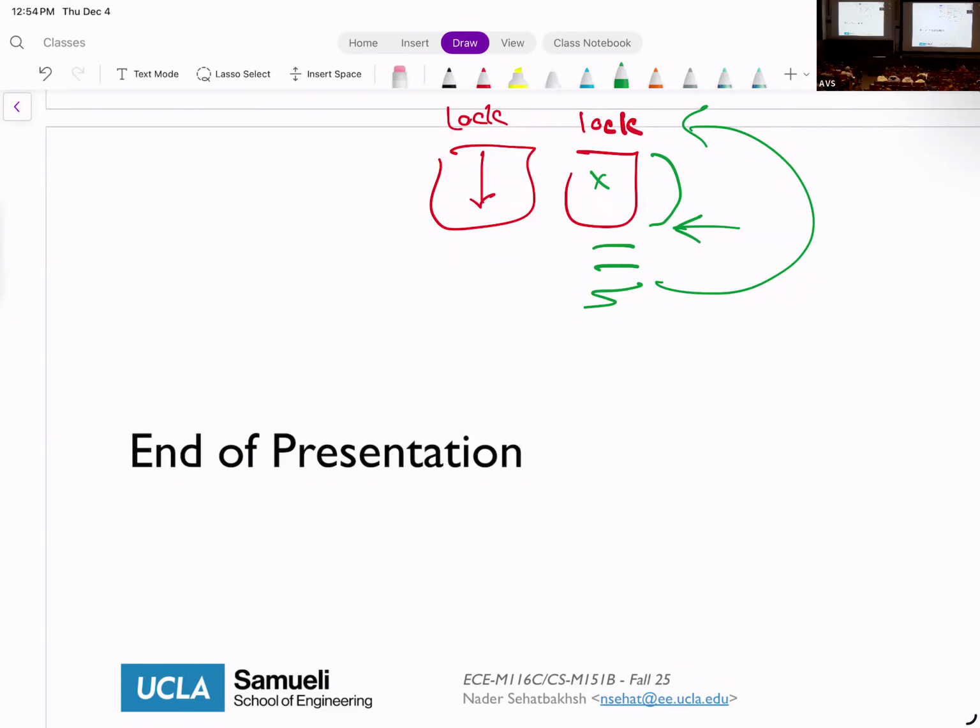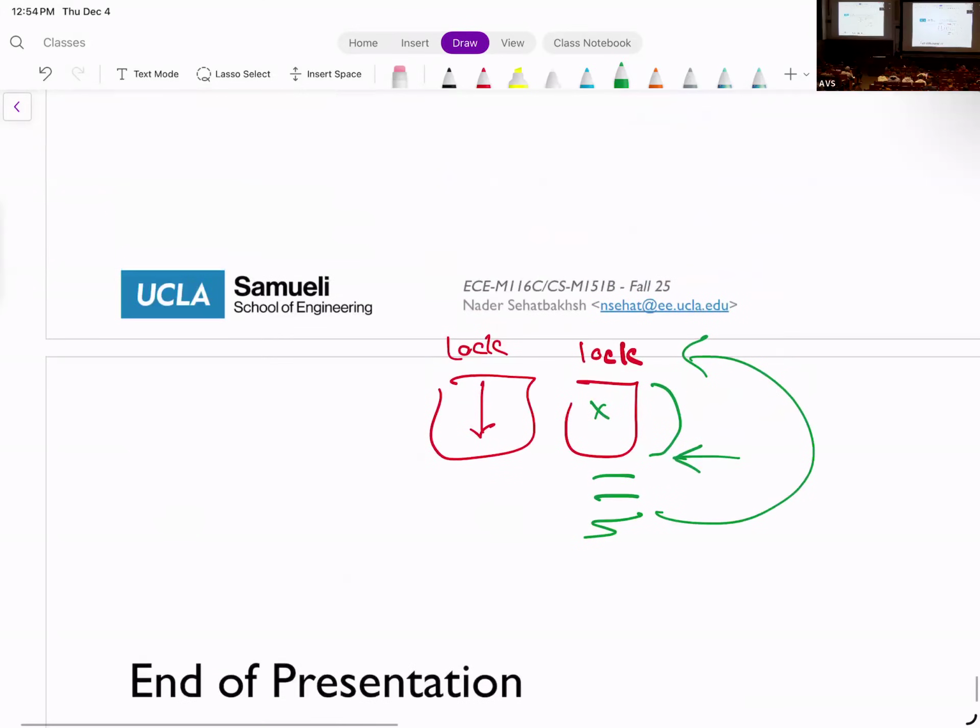If the lock is in the cache, but again, even if the lock is in the cache, you need to have a coherency protocol, because these are the same address, right? The lock is always the same address for all of them. You cannot have your own lock locally stored and the other one has its own lock locally stored, because these two things need to be the same thing. Otherwise, everybody thinks that they have the lock and then you're messed up. So it's still the coherency protocol and all that. Usually what happens is that once the write goes to M, the other one goes to I, so it has to invalidate itself in the cache.